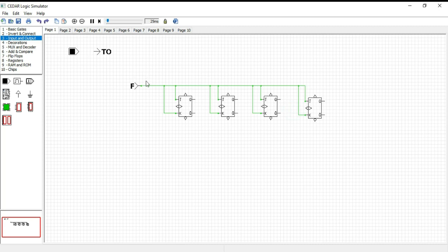Okay. Now I'm going to give names to my inputs. I add the name as in. Okay. So this is also in, and connect it with my toggle switch. Okay. Hope you all know the output of the first flip-flop will be the clock input of the next flip-flop. So it is an asynchronous counter. Okay, let's connect it all.